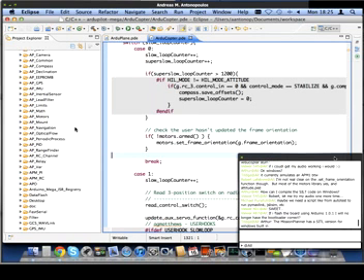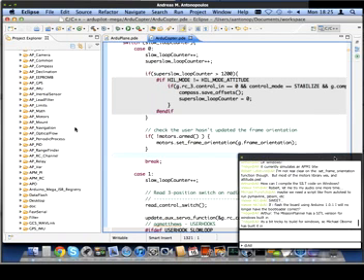If you connect to either of those TCP ports with a ground control system, such as Mission Planner, QGroundControl or MAVProxy, that will allow you to control the vehicle just as if it was connected over telemetry. Using a joystick, for example, in Mission Planner, you can push right rudder, arm the motors, and take off, and it will fly around.